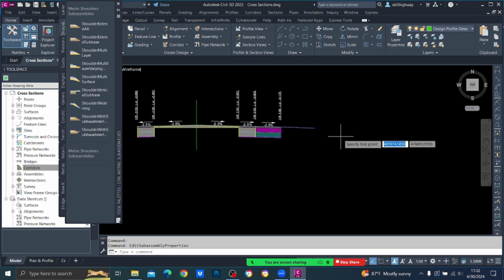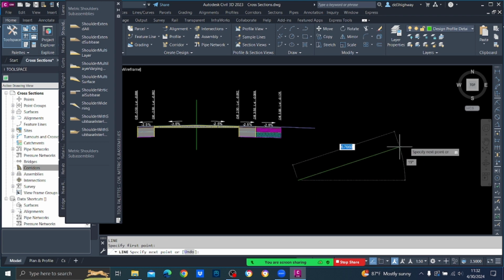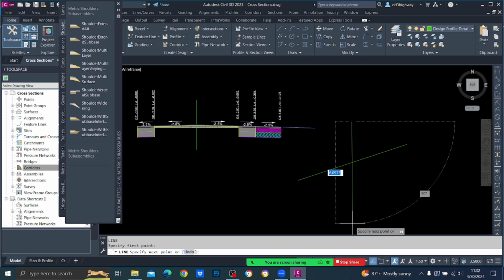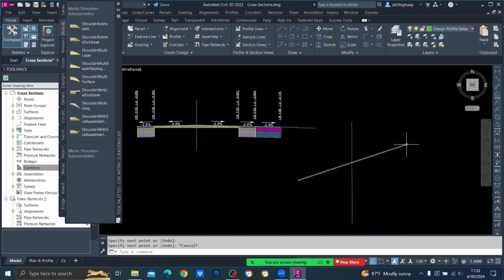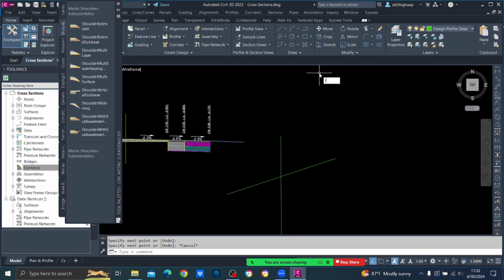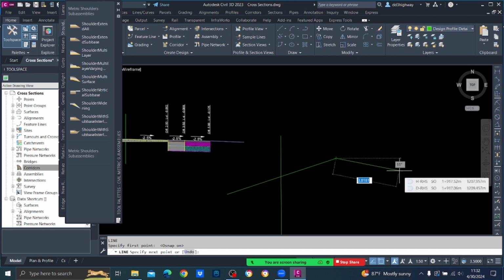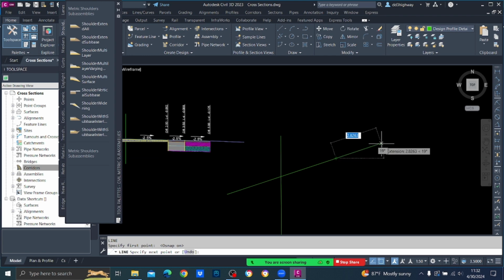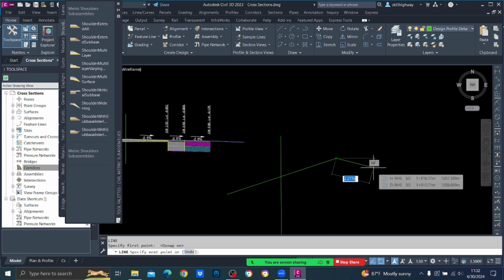Apply. Okay. So what is this maximum breakover? Now you know, when a road is super elevated like this, okay, this is the center line, this is the road. Now what about our soft shoulder? Do we keep it like this or like this, down or up? You have to keep it down. Otherwise, what happens if you keep it like this? Once the rain pours, all the debris will come to the road. Therefore, we keep it like this.